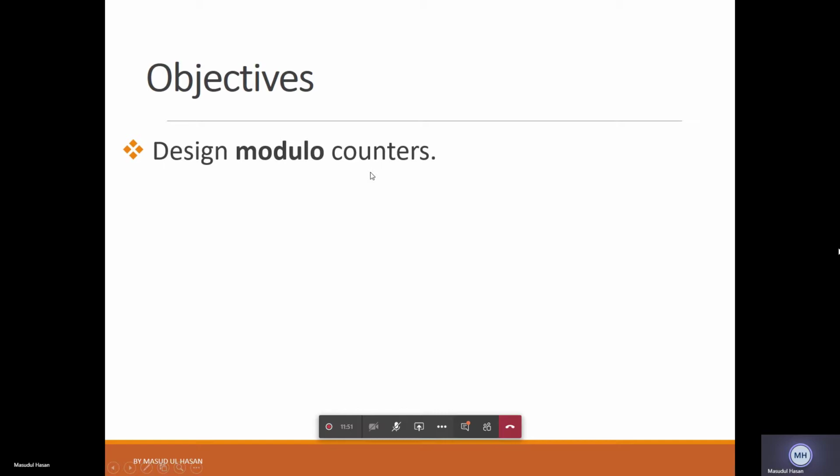So if you are doing this experiment using schematic, yes, you need this bus tab. Why? Because we need to feed this to the 7-segment display. And if you remember, the 7-segment display has 4 inputs, 4 digits, right? D0, D1, D2, D3. So if it is the least significant, it will go directly to D0. 4 bits will go to the 4 bits of D0.